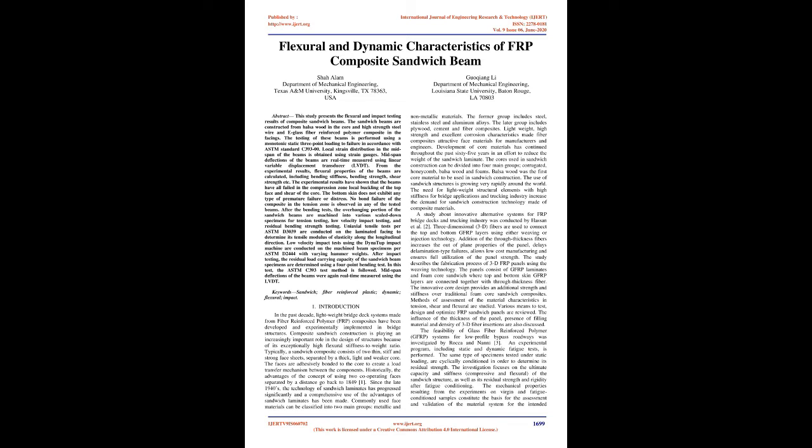The experimental results have shown that the beams have all failed in the compression zone, local buckling of the top face and shear of the core. The bottom skin does not exhibit any type of premature failure or distress. No bond failure of the composite in the tension zone is observed in any of the tested beams.